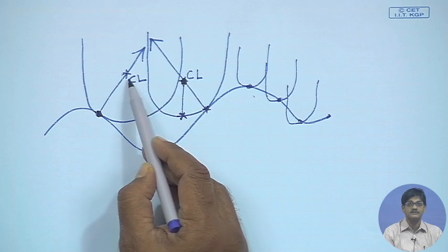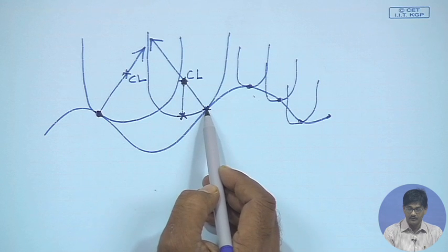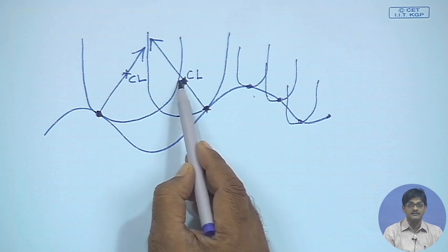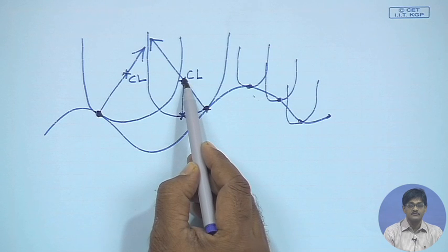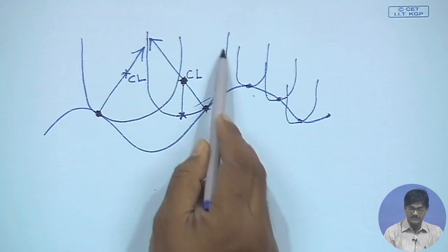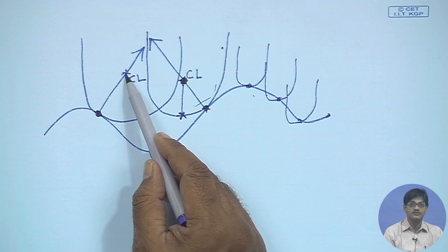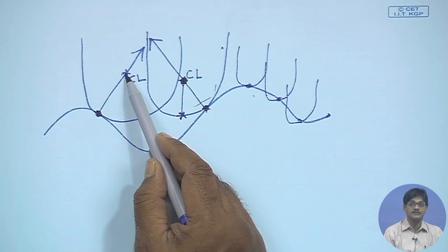There can be no two positions. It is completely in contact with the surface at the cutter contact point, and this is the location of its central position of the spherical end to fix it in space. So, cutter location points are the ones which should be given to the machine control.